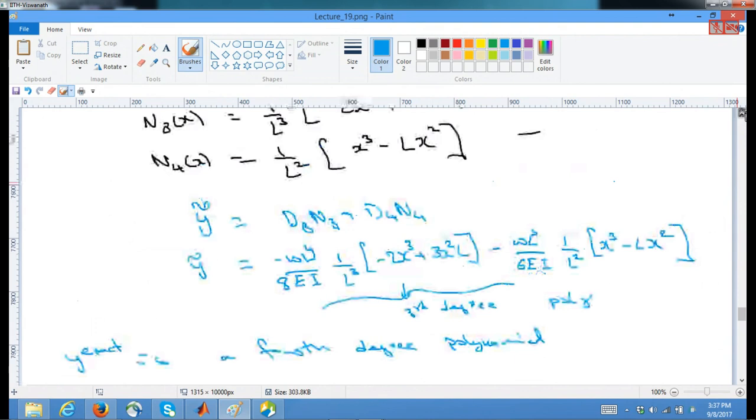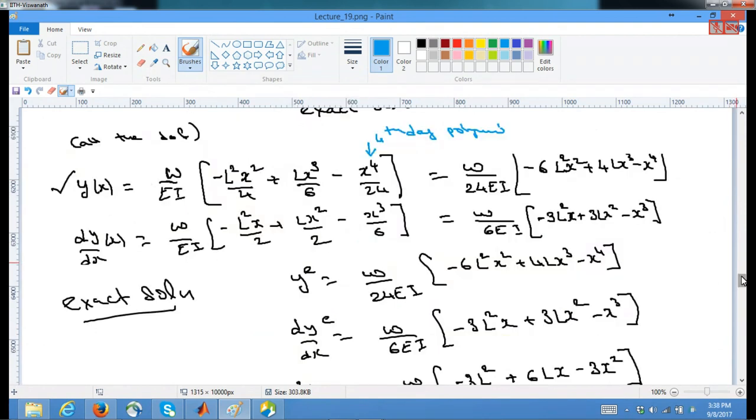The feature of this FE is that at the nodes our equilibrium is enforced. That's the reason the nodal solutions would match. That means at the nodes you should get an exact solution, while in between the nodes it is not guaranteed the solution is exact, because the solution in between the nodes is purely an approximation.